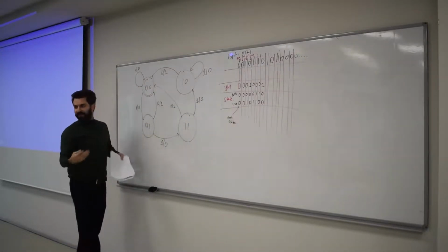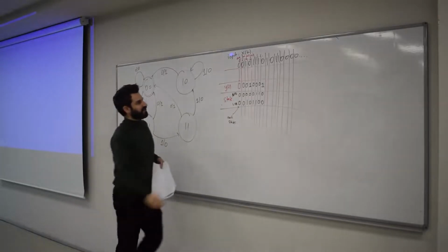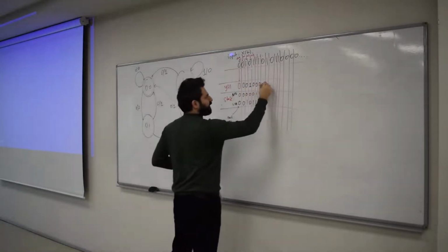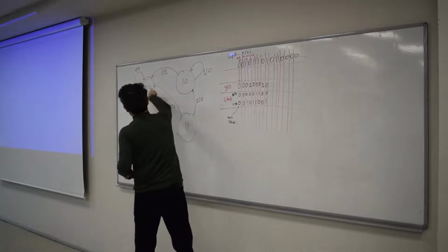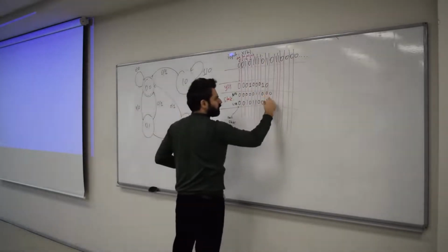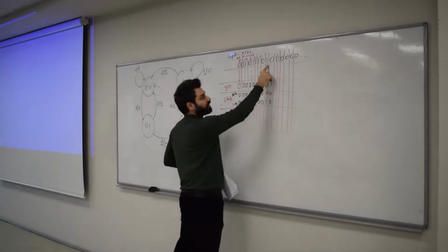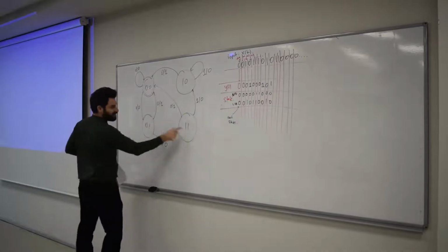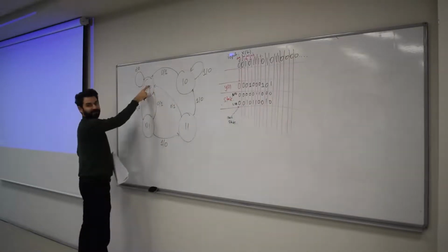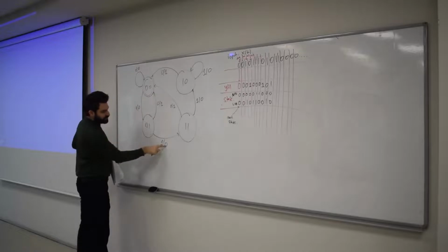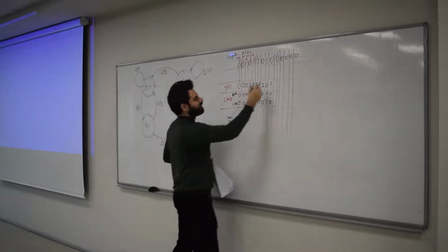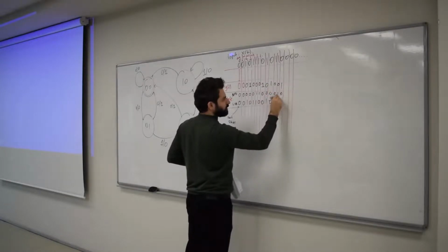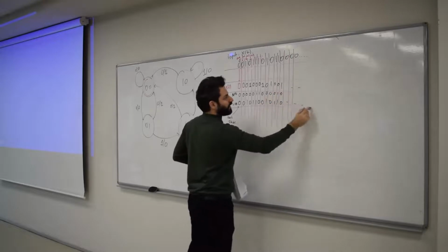So I'm actually now getting a bit speedier because we've covered that case. So that means 1 is going to put me to 0, 1 state and create a 0, and then that 0 will push me back to the initial state, which will 0, 0, but that will create a 1. Again, because of this one now. All right? And continuing that way, 1, 1 will push me here, and then 0, go back here, right? But that would create a 0, 0, 1. Okay? So this is 0, 0, 1, and this would push me 0, 1, and 1, 1, and then 0, 0. Okay? And it continues like that.